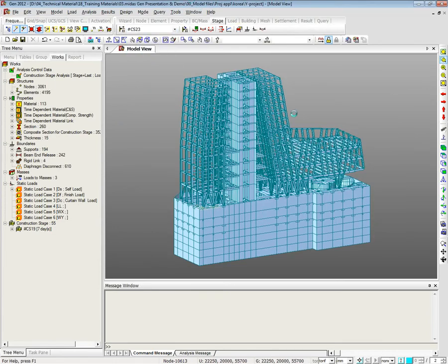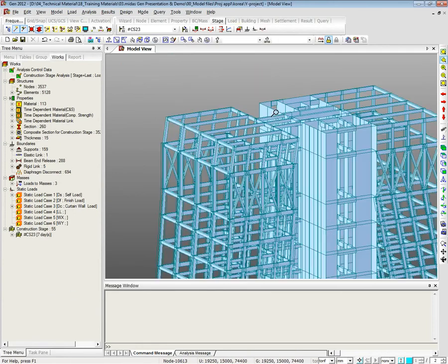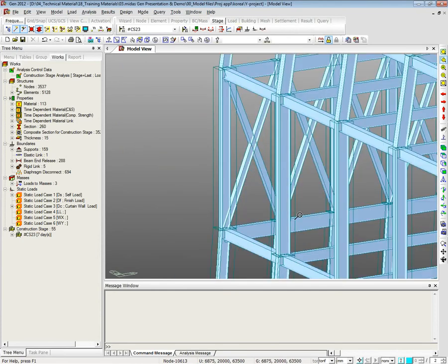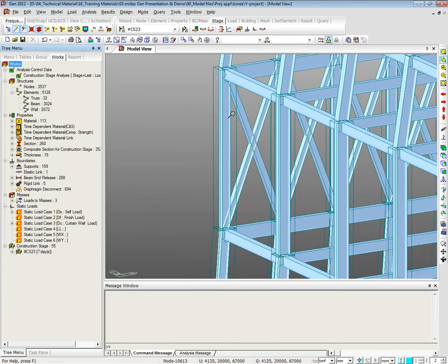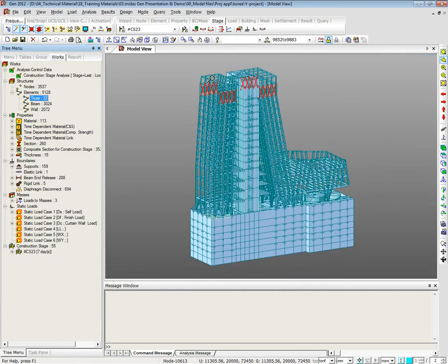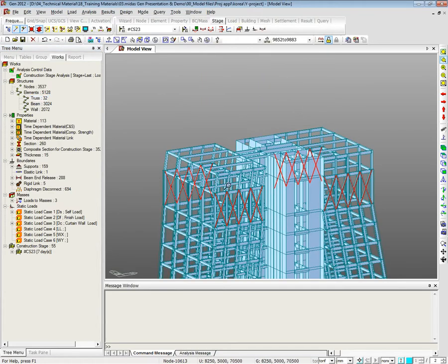And at the middle of the structure, we have the outrigger truss. If you see here, we can see the truss. And to simulate this X truss, we used the truss element, so it resists only the axial forces. So there is no special method when we consider the outriggers. We can simply model them using the truss element or beam element with the certain stiffness of their member.